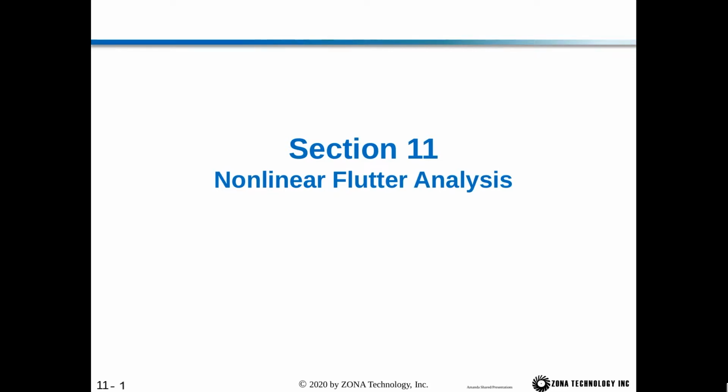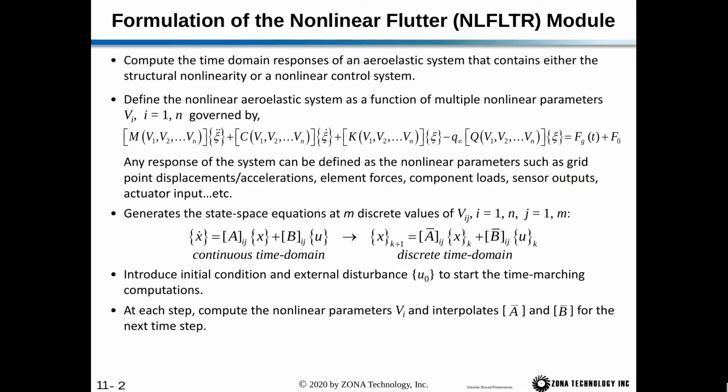Okay, let's start the last section of the ZAERO Advanced Training, Section 11, Nonlinear Flutter Analysis. First we'll go over the formulation of the nonlinear flutter module in ZAERO. This module computes the time domain responses of an aeroelastic system that contains either a structural nonlinearity or a nonlinear control system. We do that by defining a nonlinear aeroelastic system as a function of multiple nonlinear parameters, Vi, where i is 1 through n, governed by these equations.